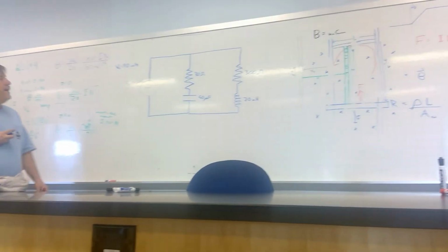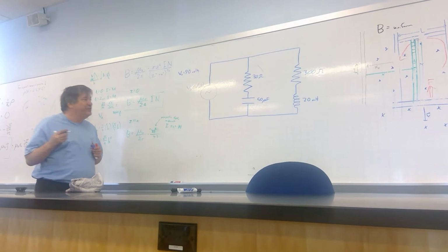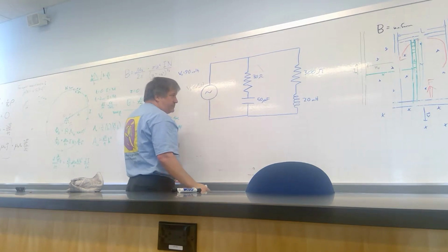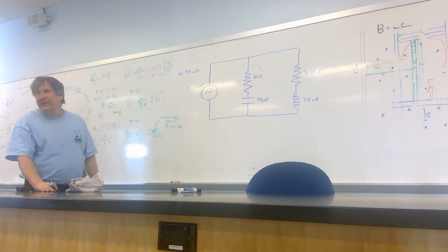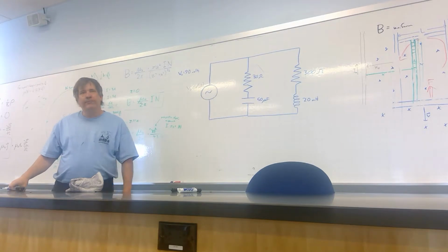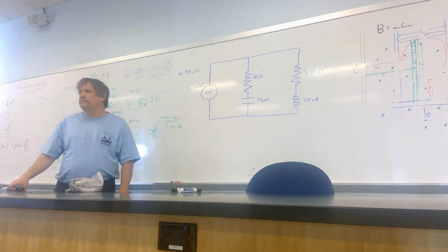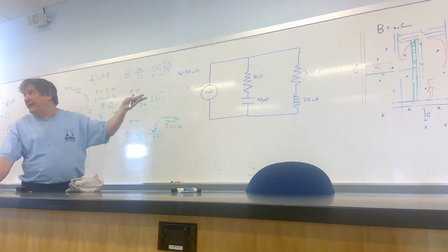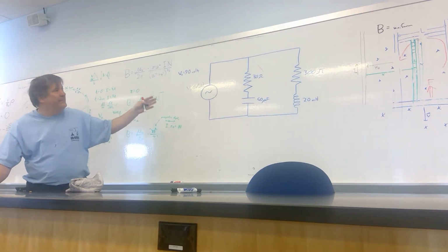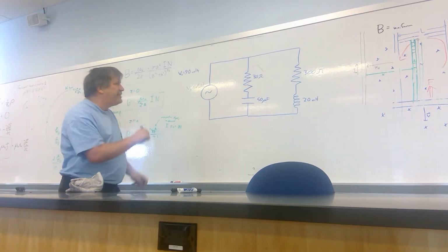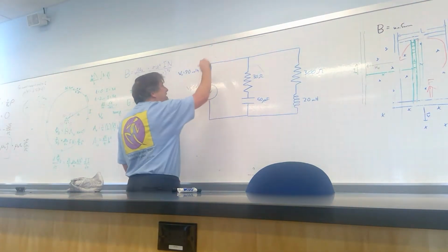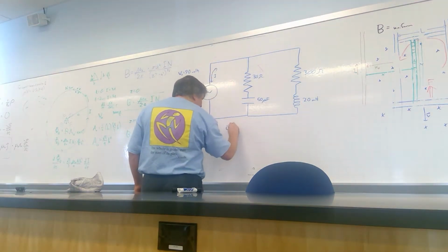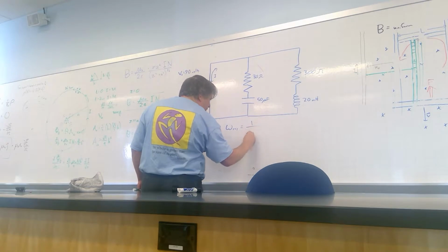so here's my circuit. A couple things I could ask you about this circuit. Okay, first off, what do you think the resonant frequency of this circuit is? 1 over the square root of LC, right? Yeah, I know this is not a perfect series circuit like we've seen before, but even for this slightly different setup, the resonant frequency, the one where I would get the strongest current flowing in and out of this power supply, is still going to be 1 over root LC.